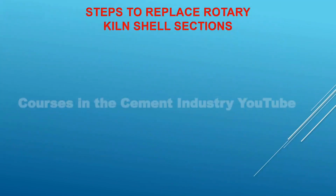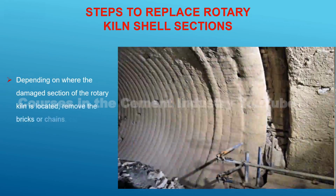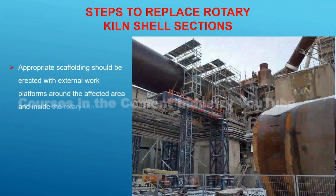Step 2. Depending on where the damaged section of the rotary kiln is located, remove the bricks or chains etc. and perform a thorough cleaning. Step 3. Appropriate scaffolding should be erected with external work platforms around the affected area and inside the rotary kiln shell.